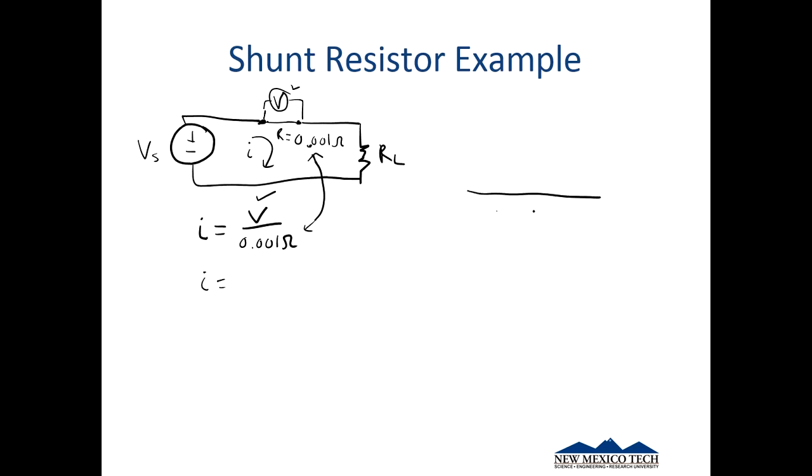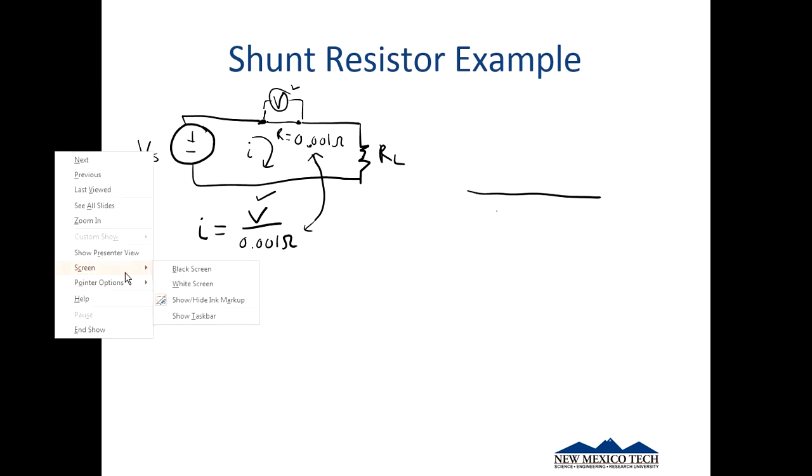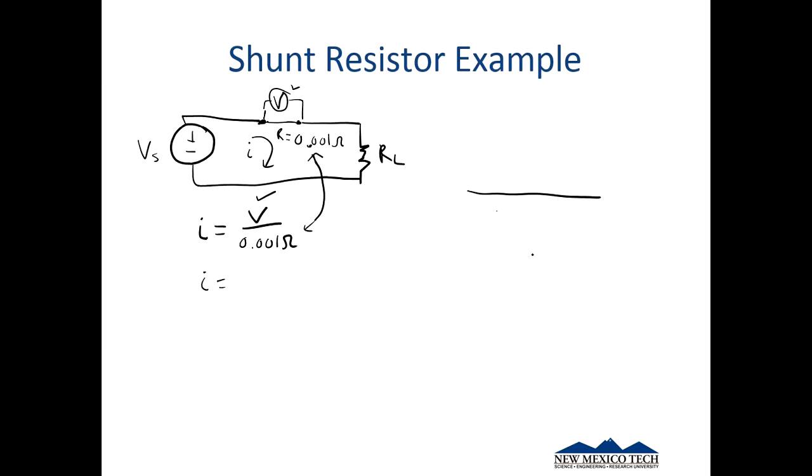There is a clamp type, so if this is your wire, suppose that's your wire, there's a clamp that clamps over it, and basically measures the magnetic field, and you can find the current that way. And that's great for spot checking things.